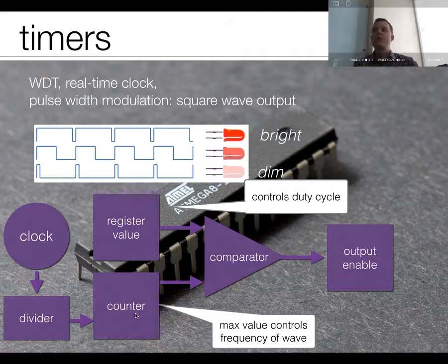First of all, do we know what pulse width modulation is? We're just controlling the width of that pulse. The way that we're doing it is by having a value and a counter. All we're doing is comparing the value of that counter to the value that we've set here. If they ever get above each other, then we output high. And this just keeps repeating. We have this counter that's doing nothing but repeating. So if that counter can only go from 0 to 255,